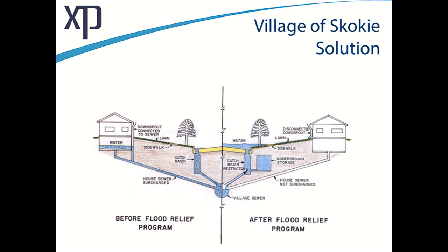And finally, the last thing I wanted to show you was a solution from Skokie. The reason Skokie is so near and dear to my heart is I've worked 14 years on it. I'm still working on it. It's been almost 20 years now. And to give you an idea, they had water back up in their basements. They stored water on the street and in underground storage, and by controlling it at the source, releasing the water at a controlled rate to not surcharge the sewer system. And once again, I have an example of the Skokie project for you.